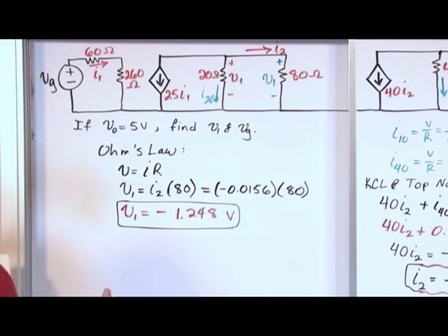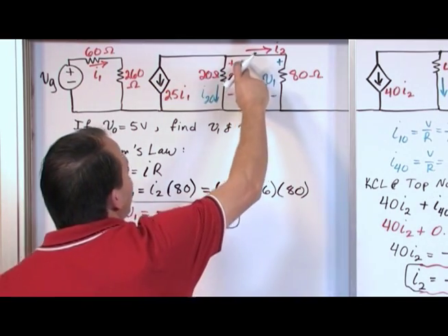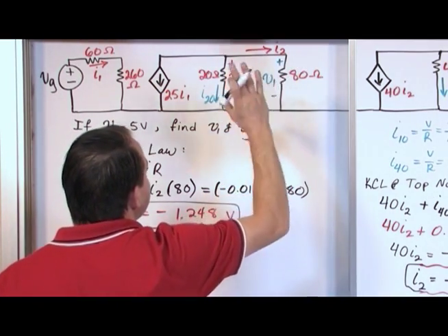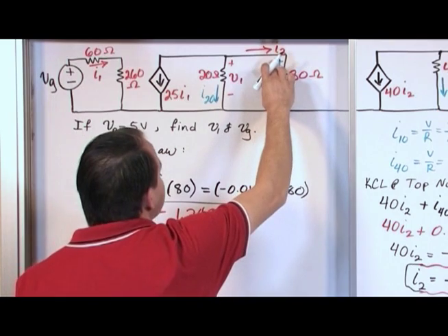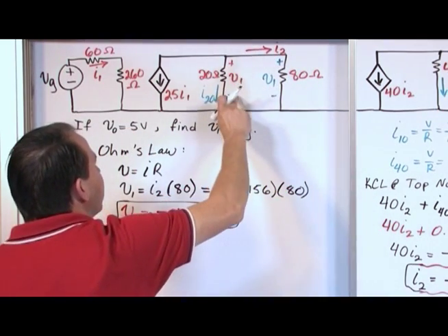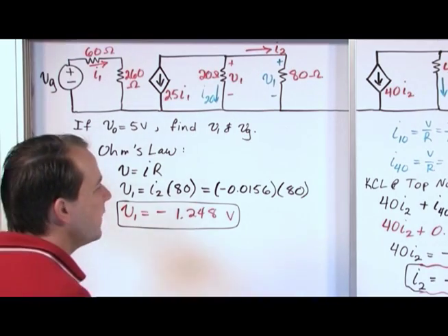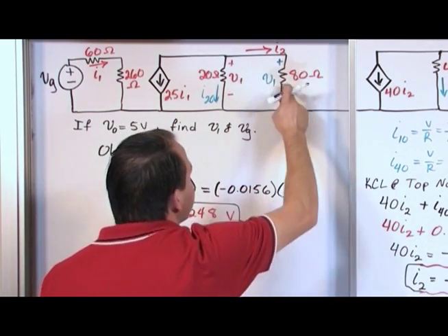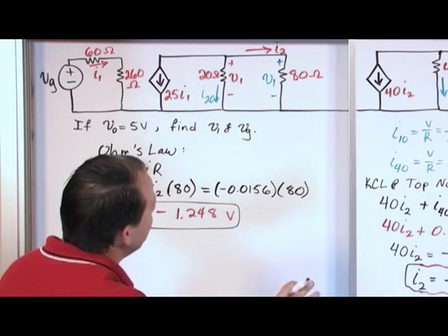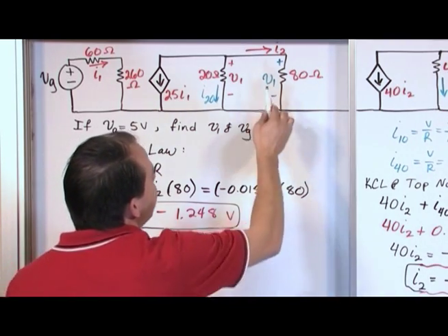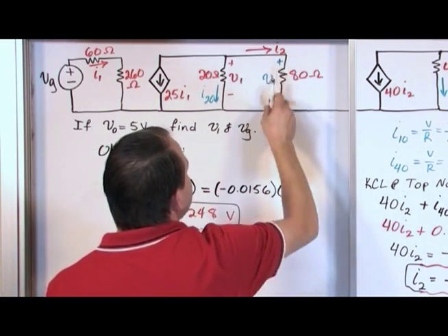What does that really mean? It really means that this voltage isn't really, if you drew the circuit and you built it, isn't really in this direction. It's really flipped around, where this is positive and this is negative. Why do you think that's the case? The reason is because this current is not really flowing in this direction. So I don't want to redraw it and clutter things up, but what it's really saying is this current isn't going down, this current's really flowing up.